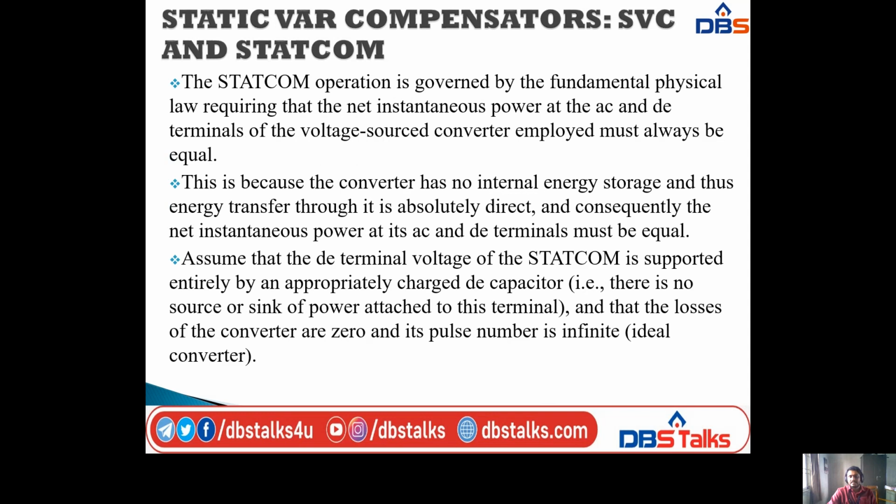The STATCOM operation is governed by the fundamental physical law requiring that the net instantaneous power at the AC and DC terminals of the VSC, that is the voltage source converter, must always be equal. This is because the converter has no internal energy storage. Thus energy transfer through it is absolutely direct, and consequently the net instantaneous power at its AC and DC terminals must be equal.